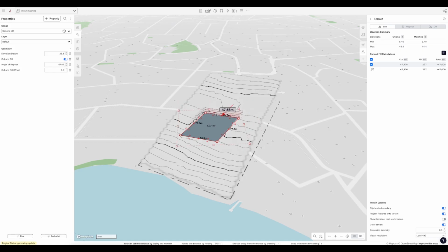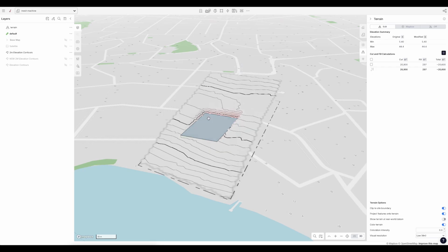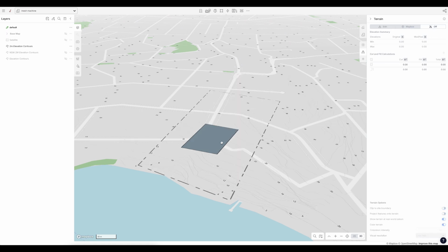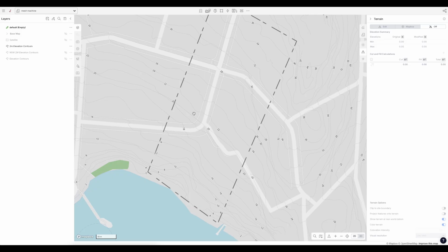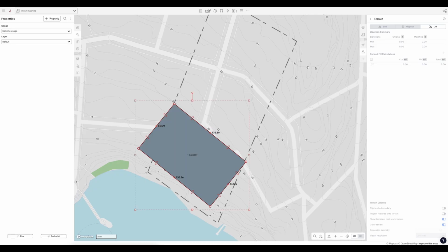So that's the first way of dealing with elevation in Giraffe. Quick, diagrammatic, slightly quantitative, but not extraordinarily accurate. The second way of dealing with elevation in Giraffe is even more diagrammatic, but sometimes very useful. And that's just to use the roof tool to draw a slope.